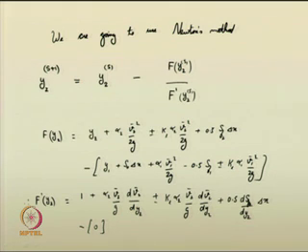So, using these expressions, you substitute them in Newton's method and improve on the iteration. You can start with whatever depth you had been provided for section 1 and give it as an initial guess for depth y2 and start the iteration.